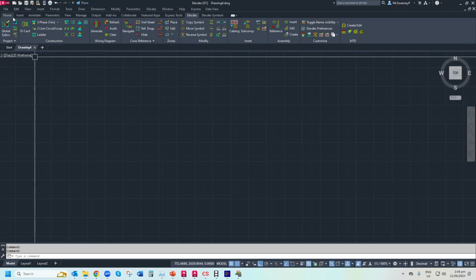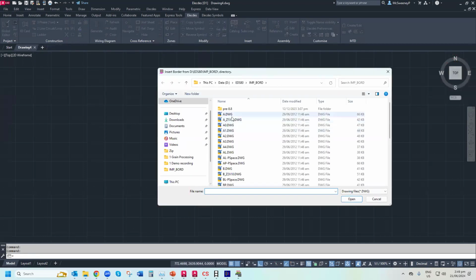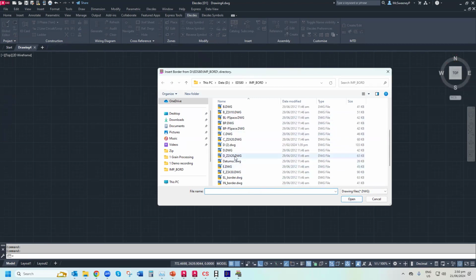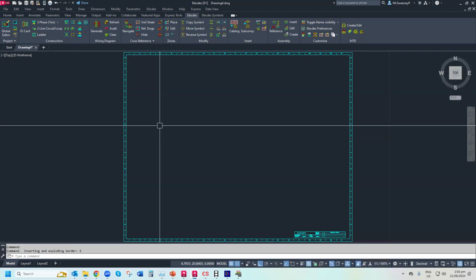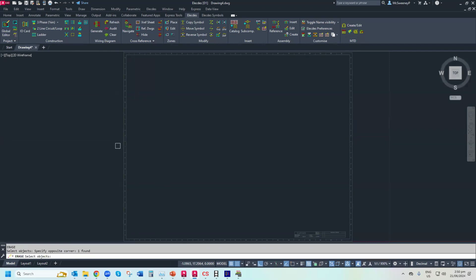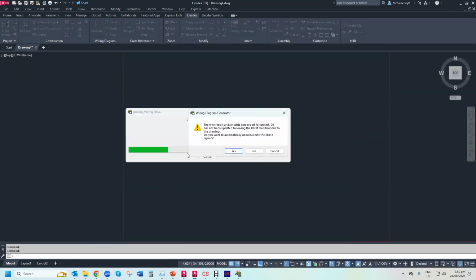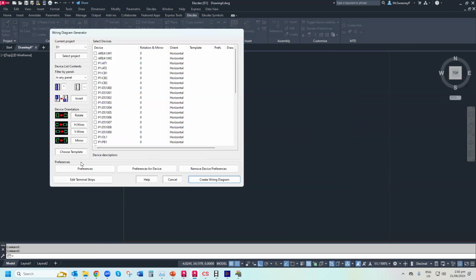All right, now the other thing I'll just finish off here is I'll put in a big size, an E-size sheet, which I'm now going to delete as soon as I put it in, just for economies of scale. Arrays, wiring diagram and terminal strip generation. I've already showed you it can generate things for things like Schweitzer relays, but first of all, let's have a look at my terminal strip. Remember, my terminal strip was TB10 that I changed at the start.